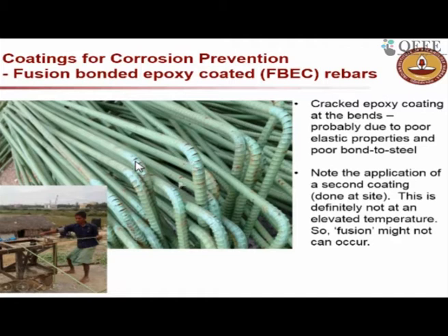My opinion here is that unless we are really able to produce quality epoxy coating, which means crack resistant epoxy coating, and enhance the handling, or consider it a very delicate piece on site, we should not be using epoxy coated rebars. You can very clearly see here on these bars there is corrosion starting, brown stain, you can see it has already started rusting.